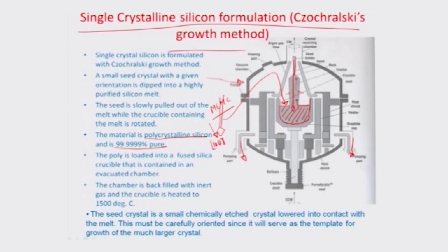Okay. So, this is the Czochralski crucible process. The seed is the mother crystal which would eventually result in the formation of a boule of material, as indicated by this outline that I am drawing here. Okay. And all the material in this boule is grown in the direction of the seed crystal, and the parent direction is kind of grown into this particular boule. So, once this boule is extracted, you can actually